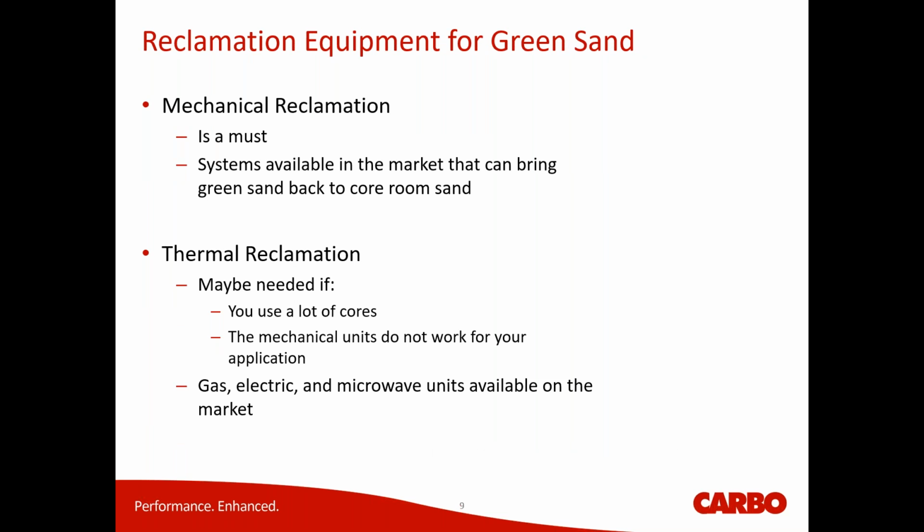Reclamation equipment for green sand. Mechanical is a must, and it's much the same reason as with no bake. You're going to get clumps coming out the backside that you need to break down. So you need something that can get them down to a manageable size before you put them through any other equipment, or you run them back through to make another mold.